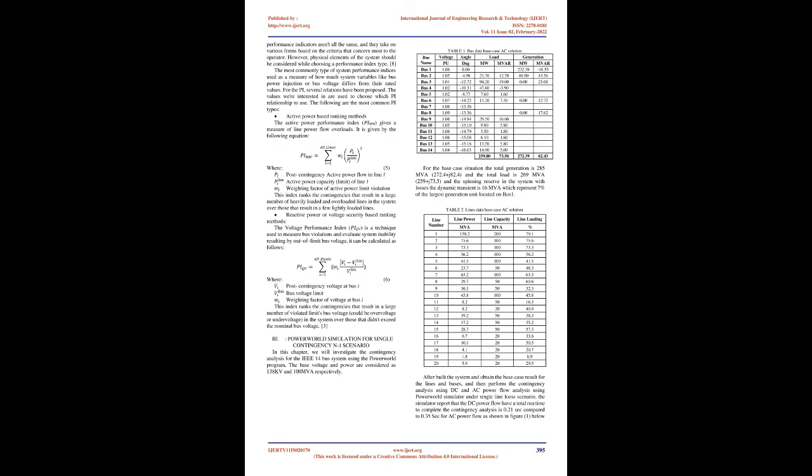Linear sensitivity factors. Linear sensitivity factors (LSFs) are calculated using DC flow analysis, which ignores bus voltages and MVA flow and estimates the MW flow in each branch with a 5% accuracy. To evaluate the critical cases, a method is formulated to rank the contingency scenarios in such a manner that only those that are likely to result in limit violations need to be investigated in more depth, while the others are neglected.